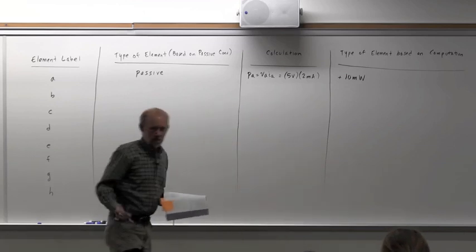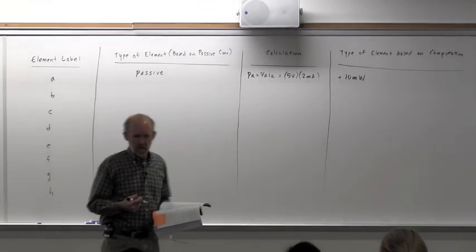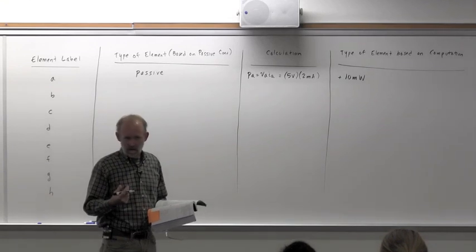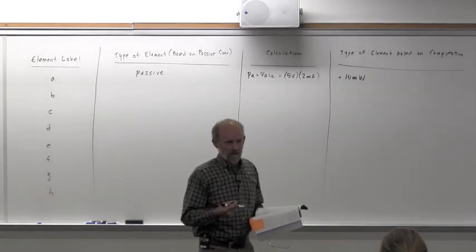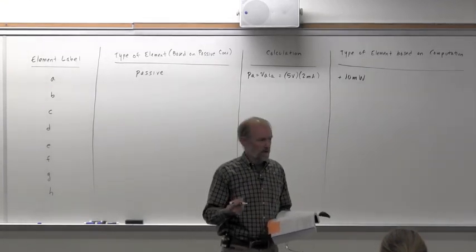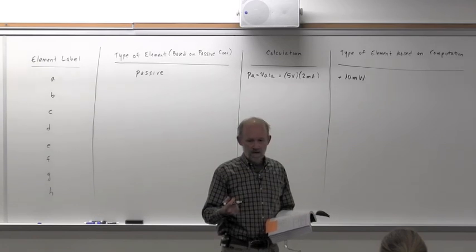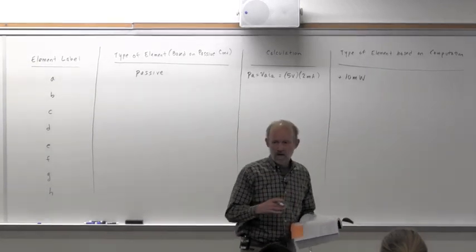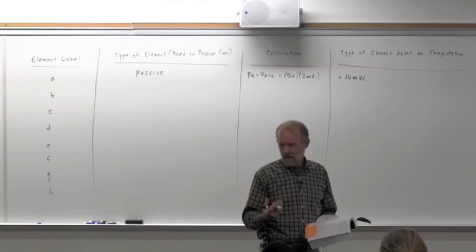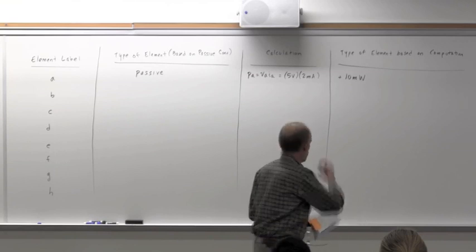So what is the element based on that calculation or computation? What was our statement in terms of the passive sign convention? Positive number means what? Anytime you see a positive value, you know that element is absorbing power. So it absorbs power.